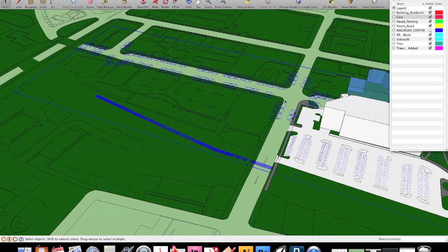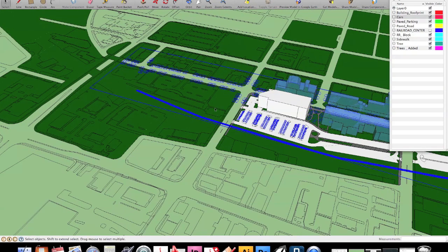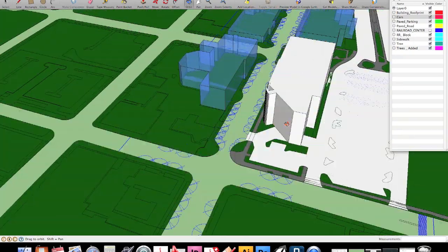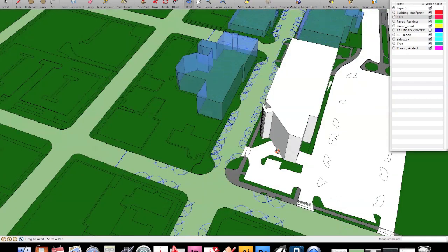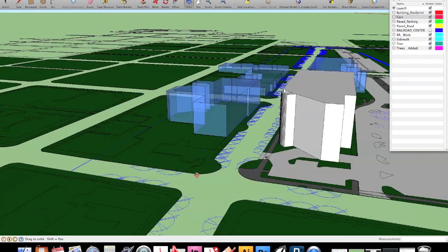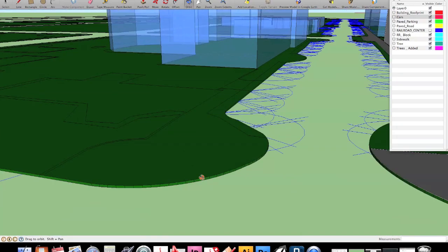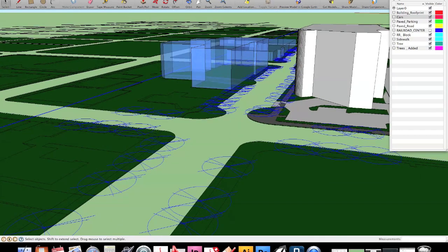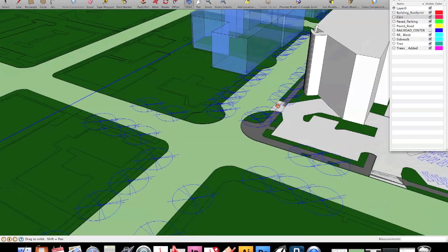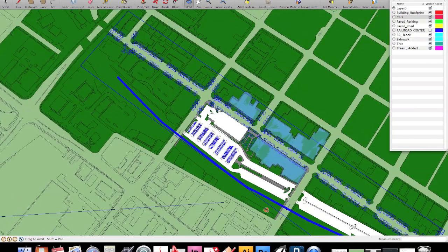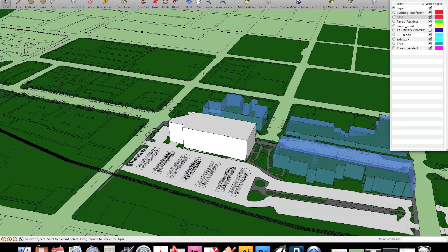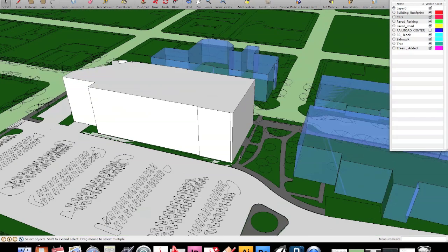We're just going to come in, and all of those were imported as one CAD file. So all of those blocks were imported as one CAD. I blocked all of those layers out at once, so again, let's just move those up 0.5 feet, or 6 inches. So now I have all of these symbols on my surface. And honestly, that doesn't look too bad as a model, does it? You know, you're starting to get the idea of the space.